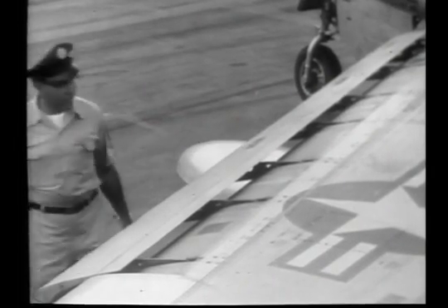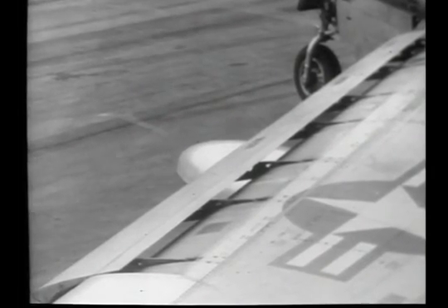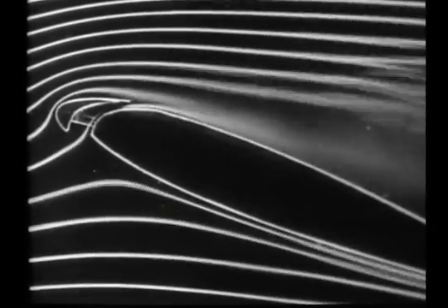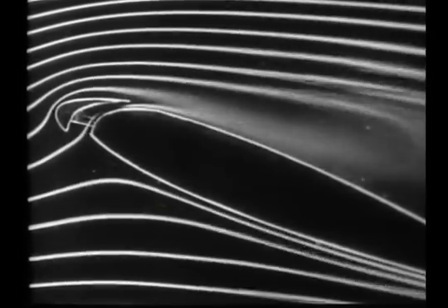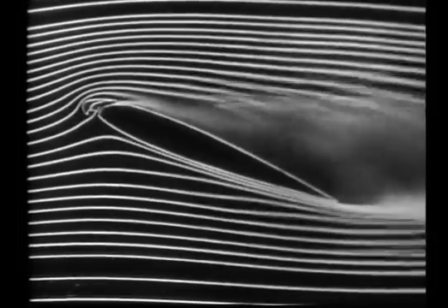The leading edge slat leads air from a region close to the stagnation point through a converging channel and ejects it at high speed at a point of low pressure on the upper surface.